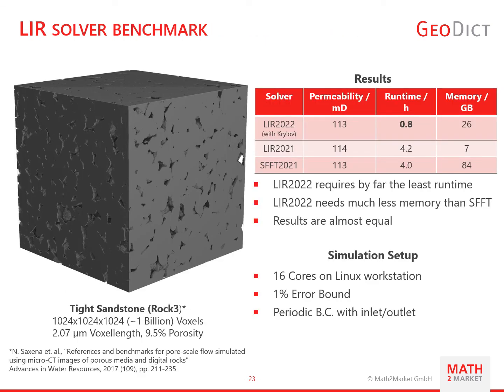Here, we benchmark the Krylov method on a tight sandstone, which is part of a benchmark paper by Saxena et al. in 2017. This rock has a very low porosity of 9.5% and is the most challenging structure of this benchmark paper. The Lear with the Krylov method is compared against the old Lear solver method and the SimpleFFT solver in GeoDict 21. As you can see in the table, the computed permeabilities are very close, but the runtime could be reduced by more than 80%, so from more than 4 hours to less than 1 hour. And the memory consumption is still much lower compared to the SimpleFFT solver.